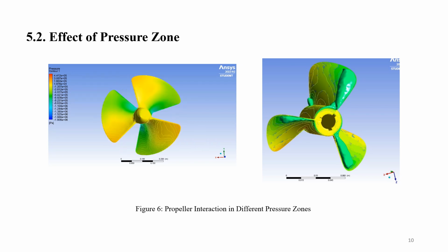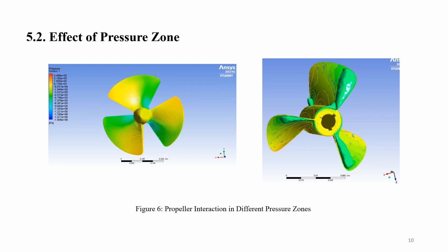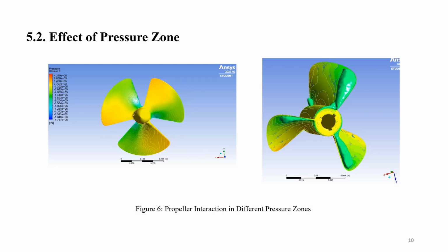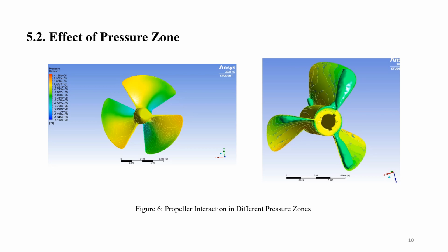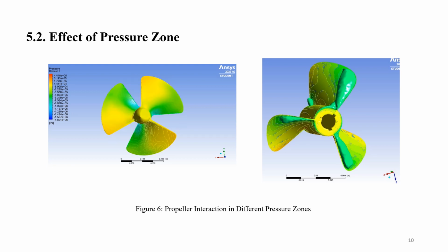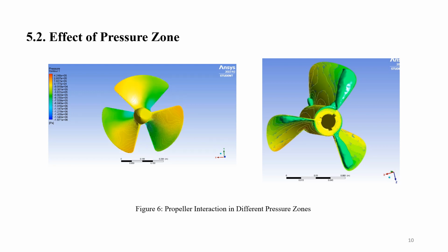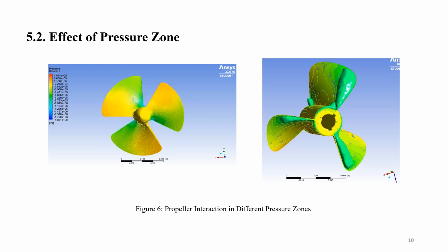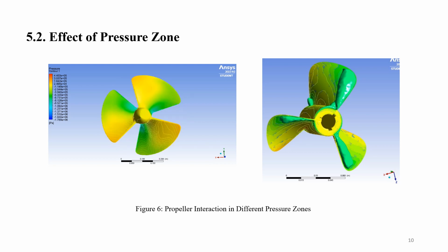Utilizing isosurface for vapor volume fraction provides a three-dimensional representation of regions where cavitation is occurring. The visualization method allows researchers and engineers to identify specific areas within the fluid domain where the vapor content reaches a critical threshold, indicating the presence of cavitation.